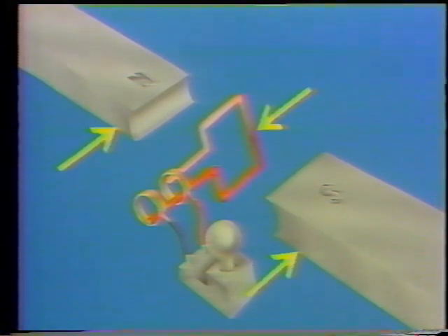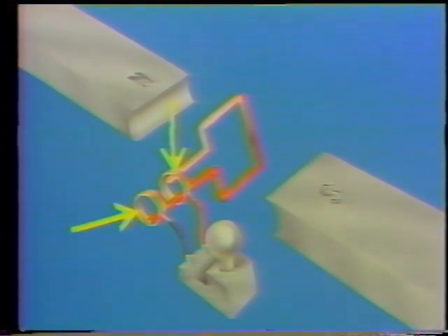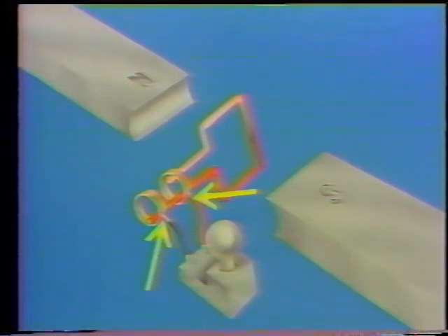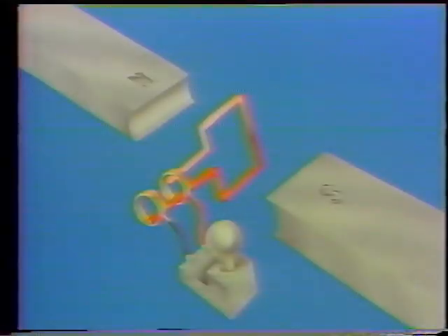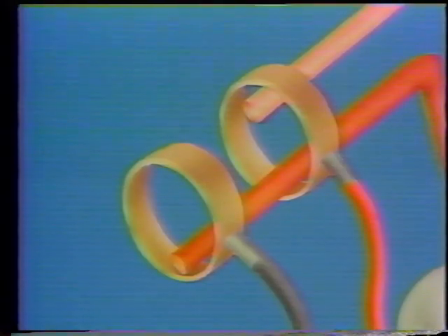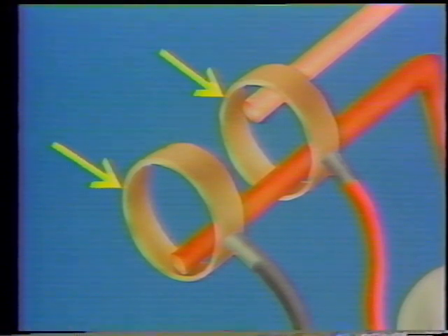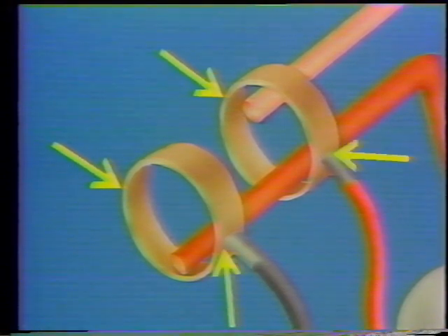and distribute. Now here we have the parts of a simplified AC generator: a loop of wire, a stationary magnet, a pair of slip rings, and a set of brushes. It's set up like this. The loop of wire is our conductor. It's placed between the poles of the magnet. Each end of the loop is connected to a slip ring. When the generator is working, the slip rings slide against the brushes. The brushes transmit current from the slip rings into this electrical circuit.